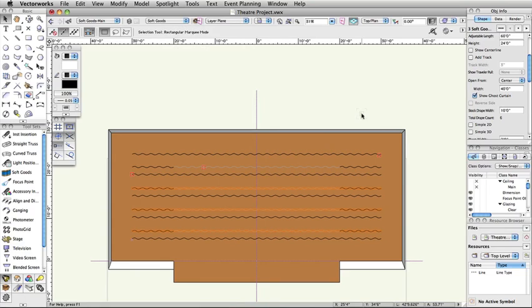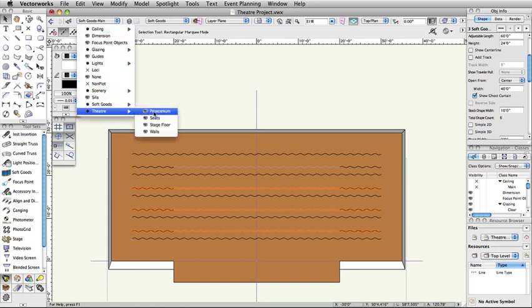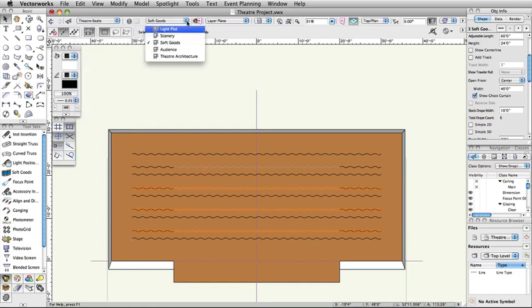The resulting seating layout object has several modifiable options, ranging from focus point, seating and row spacing, to height and rise per row. In the view bar, choose Theater-Seats from the class list and Audience from the layer list.